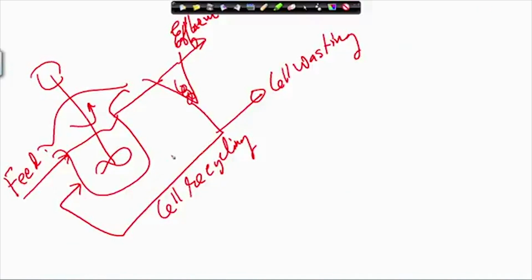Now, suppose this is the settled cell mass concentration XU, and this is X. So, when you settle, obviously the cell mass concentration will be more here, and this is the settled cell mass concentration. Let us assume the recycle flow rate is Fr, and this is F0. Okay. Then what will be here? Flow rate F0 plus Fr.